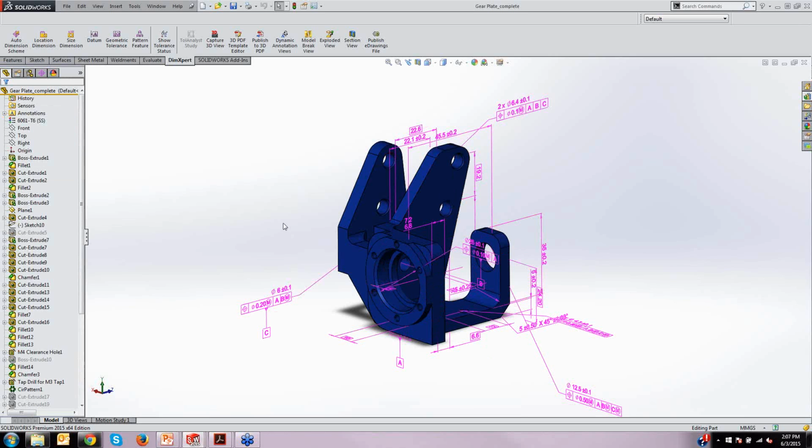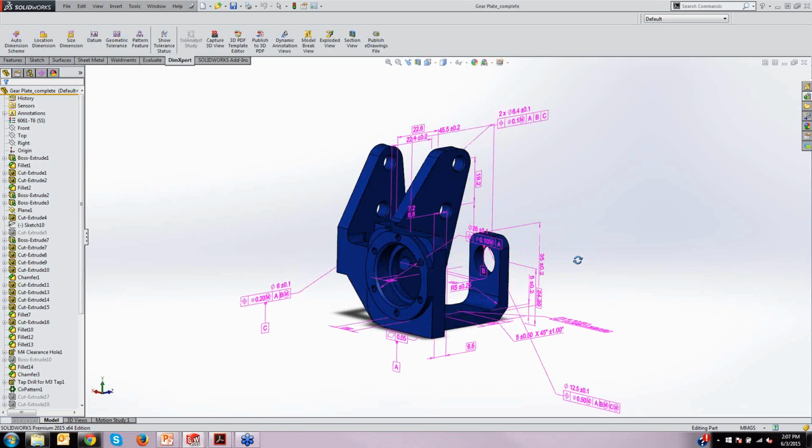This really helps anybody looking at this particular model because there is no ambiguity as to what the dimensions are pointing to. Simply clicking on any one of these dimensions highlights the feature that it's actually dimensioning. So no longer are we looking at a two-dimensional black and white drawing and wondering exactly what the orientation of the part is and what these callouts are actually pointing to. In SOLIDWORKS MBD, that ambiguity is gone. There's far more clarity. We can see that right here.